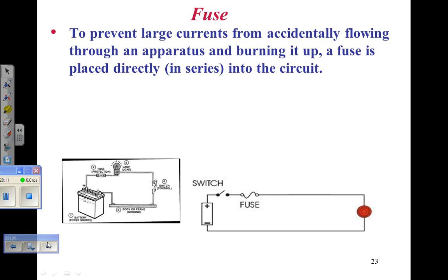Because a short circuit will not create a 22 amp short. It'll create a 100 amp short, right? It will flow lots of current. Whatever the resistance back to the source is, that is going to be how much current flows. It's going to be in the hundreds of amps, not in the amps. So a circuit breaker is set to kick off when there's a big flow instantly, in a quarter of a wave. But a little tiny bit over its rated ampacity, it's going to let it go. Let it slide, baby. It's okay. All right? So that's how fuses and circuit breakers work.